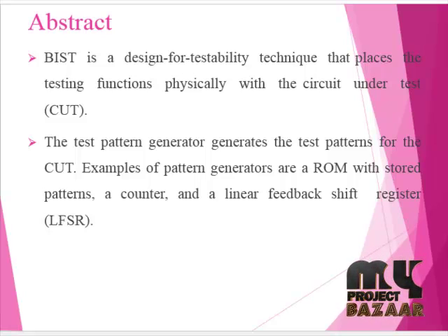Logic built-in self-test, originally developed for board, system, and in-field test, is now gaining acceptance for production test as it provides very robust DFT and is used increasingly often with test compression. This hybrid approach seems to be the next logical evolutionary step in DFT. It has potential for improved test quality. It may augment the ability to run at-speed, power-aware tests, and it can reduce the cost of manufacturing tests while preserving all LBIST and scan compression advantages.